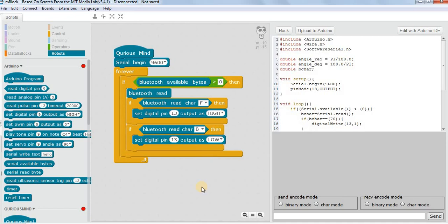So it is a simple program where we are controlling the switching on and switching off of the LED using Bluetooth. And for sending the commands, we are going to use one Android app which will send the commands over Bluetooth, which our HC05 module will receive, and we will compare the commands and we will perform the action. Upload the program, check if it works as desired. In our next program, we will control a vehicle using an Android app.